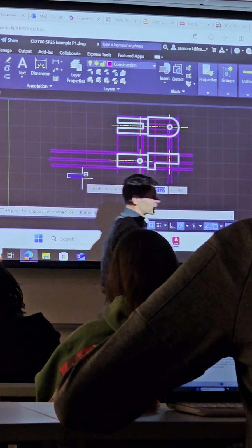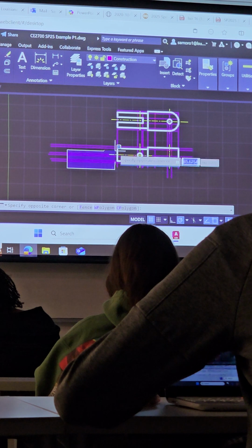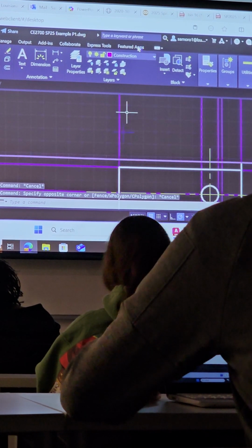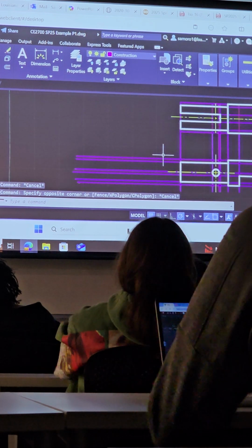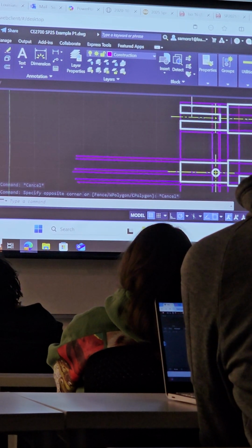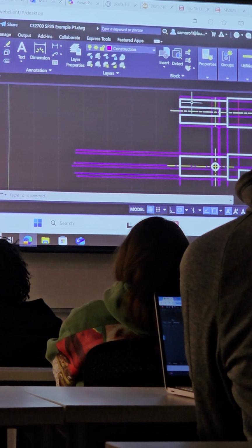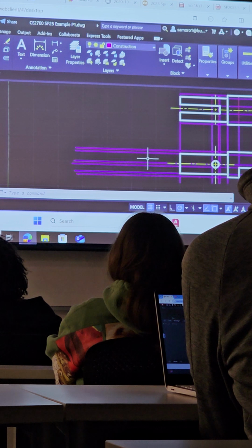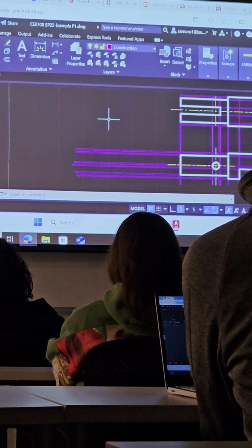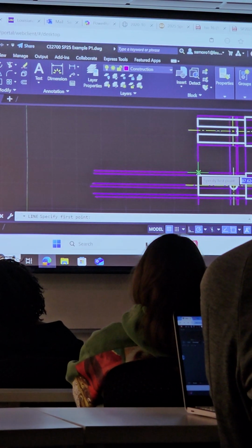I'm going to use a little trick that consists of drawing a construction line at a 45-degree angle from the corner of this view and use that as a line to reflect all of the things that are happening in this direction down to this direction. So the up-down direction in this view is going to get transformed into a left-right view down here. So the first step is to draw a 45-degree line from the corner of the object.